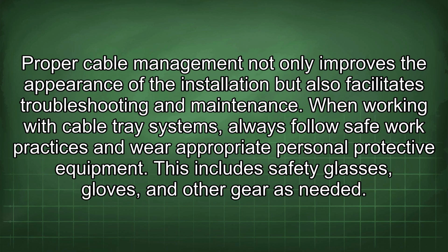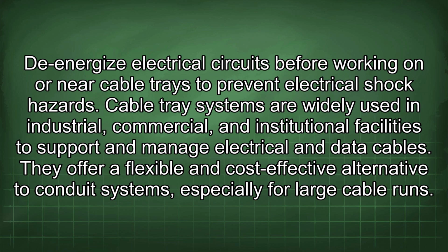When working with cable tray systems, always follow safe work practices and wear appropriate personal protective equipment. This includes safety glasses, gloves, and other gear as needed. De-energize electrical circuits before working on or near cable trays to prevent electrical shock hazards.